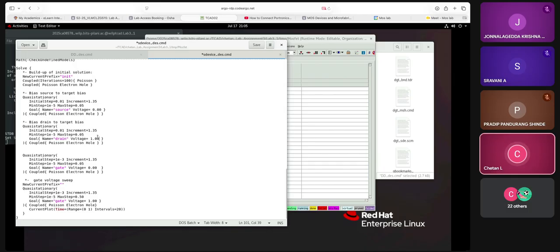The drain voltage equal to 1.00. There, what you should do, you just delete 1.00, write this at capital VD at. I'll pause here. Any questions? Let me know now. Because this is the first step for our first question of the experiment. We are asked to parameterize the drain voltage for different gate source and ID current. That is what we are doing here now.